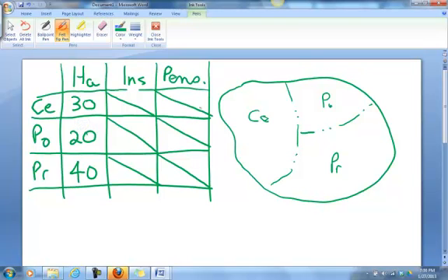So for cedar, what you're required to leave as insular, and remember, insular are islands of areas within the cut block, is 4%. And then the peninsular is represented by 16% of area we have to create, which will be like little areas that jut into the cut block.